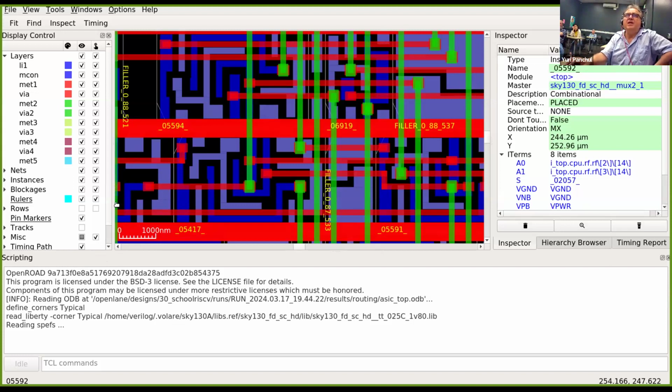They allow you to define the floor plan by Tcl commands. Usually a floor plan is a specialized file which is done semi-automatically. A specialized physical designer specifies the floor plan, but also uses a tool to make an optimal floor plan.